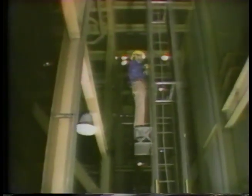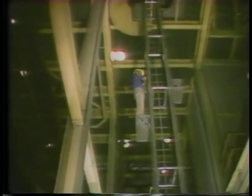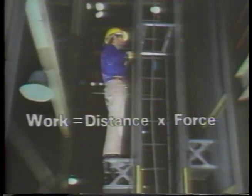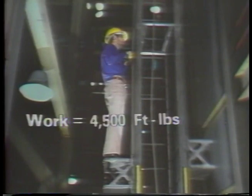Let's look at another example. In some plants, man lifts are used to travel between elevations. If a 150-pound man needs to ride a lift 30 feet to the place where he's working, how much work must be done to get him there? Let's figure it out. Work is equal to the distance moved, which is 30 feet in this case, times force, the weight of the man, which is 150 pounds. Doing the multiplication, we find that the man lift must do 4,500 foot-pounds of work in order to raise a 150-pound man 30 feet.